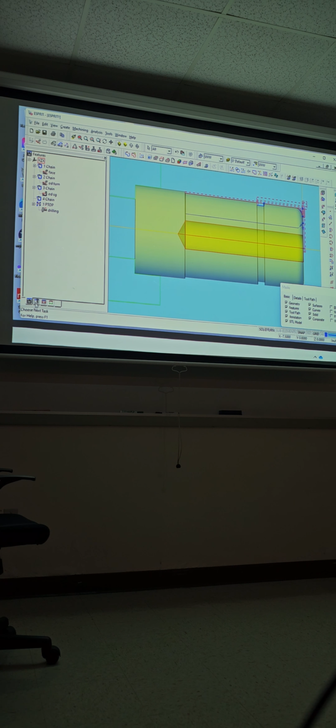Like he's saying, you have the drill right there, and you have a boring bar going in, and that drill is right next to it, it could still crash. The drill could hit that chuck. I would space the pocket. Right, but usually, you only leave that empty pocket when you transition from OD to ID or ID to OD again. All right? So, no, we don't need that empty pocket. But we're in the military, so let's be extra safe. That machine has an empty pocket between the drill and boring. Yeah, I saw that.